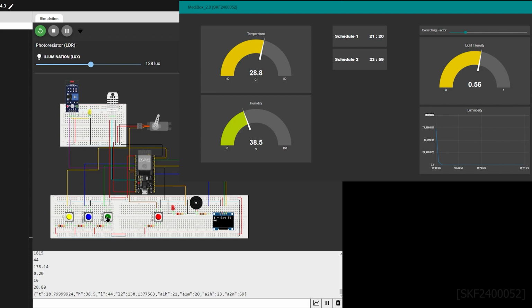The slight delays in the feedback are due to various delay functions included in the code and the linear flow of execution. This can be improved by implementing multitasking methods like RTOS.